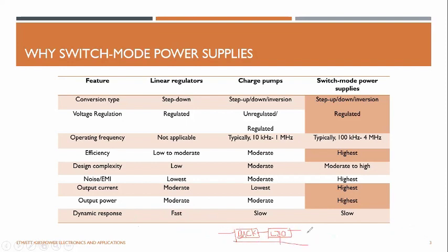Then you can get a very good dynamic response, even though the efficiency might be 1 or 2% lower than using just the buck converter. When you add the LDO regulator, you reduce the efficiency slightly, but you get a nice and fast transient response with a very low output noise. That is called post regulation. It's a common thing in power electronics. Most power electronics engineers are using that technique.